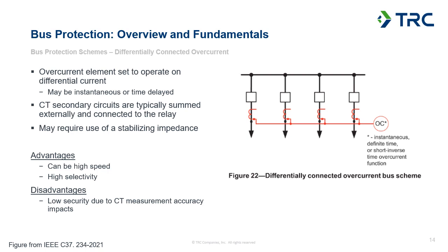So that's the main disadvantage, and because of that disadvantage, we don't really see a lot of utilities using this as a new scheme. We interface with these occasionally on an existing substation, but generally we're not going to be applying new differentially connected overcurrent schemes.